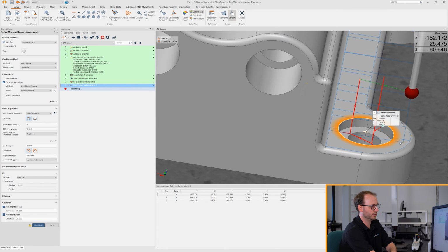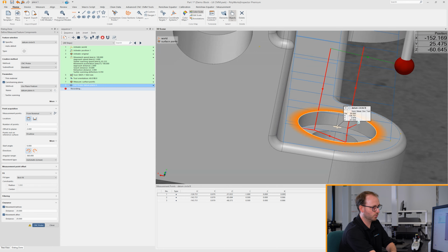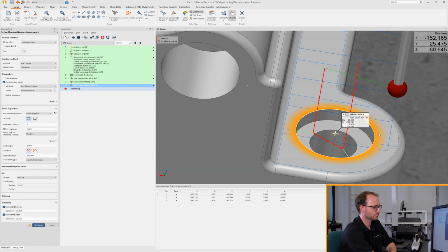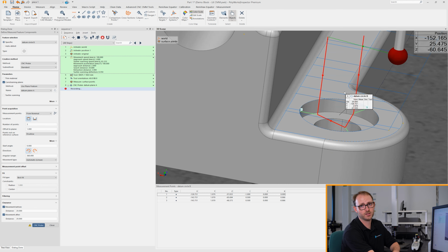And then you'll still see we have some red on our toolpath. So what I'm likely to believe here is the points are too close to the bottom for our collision. So the first thing I will do is the offset to plane here. I'm going to change that so it's on 1 millimeter. And see we're green again. So now that I've changed the offset to plane, you can still see we have some red here, but what I'd like to show you, so down here in the bottom corner,